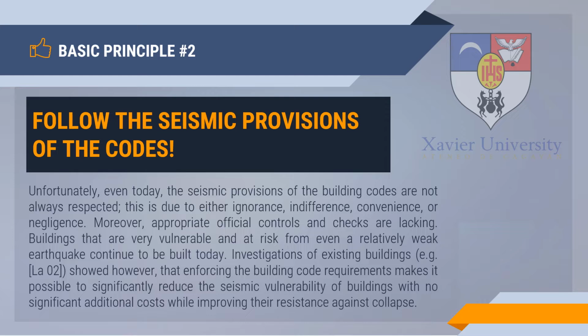So today, the principles of capacity design together with the concepts of ductile behavior allow a safe and cost-effective earthquake-resistant design. So the latest efforts of seismic code development were mainly focused on internationally harmonized standards like ISO 3010, Eurocode 8, and UBC.